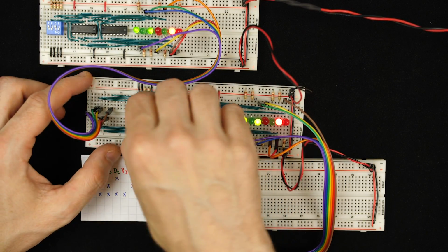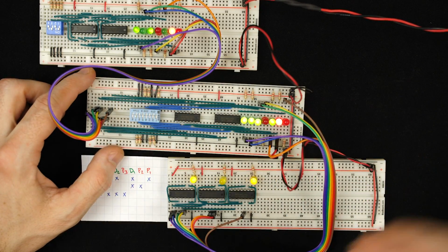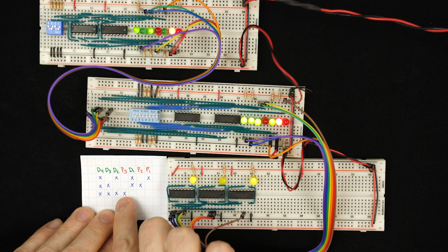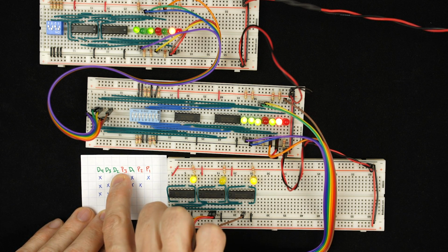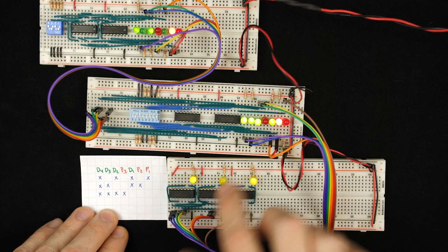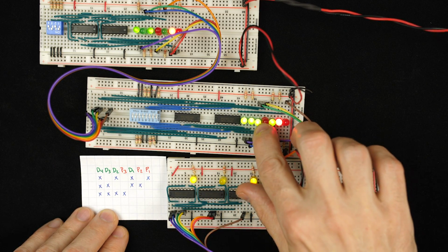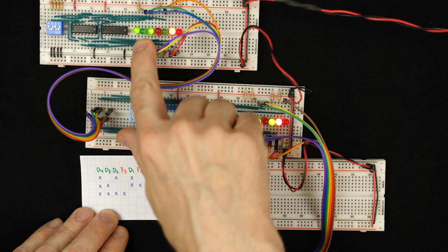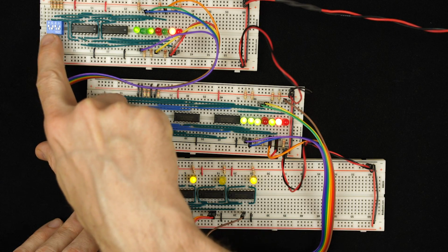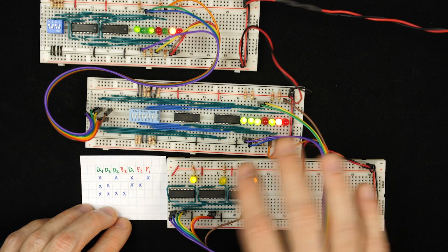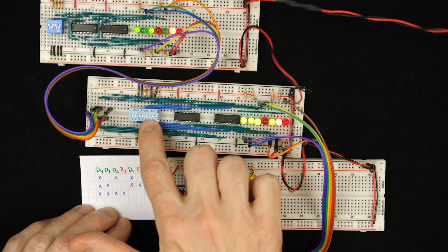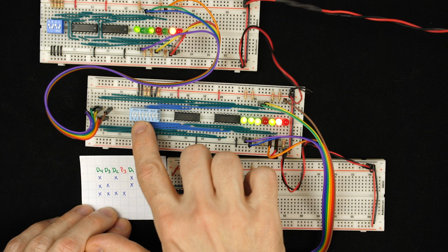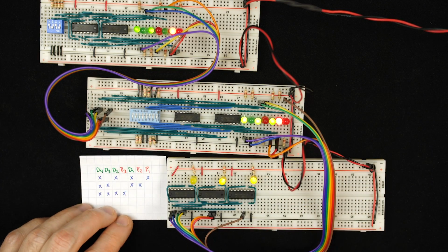Now, obviously, the one caveat is if there are 2-bit errors, then all bets are off. In this case, we're seeing parity bit 1 and 3 are wrong. The case where parity bit 1 and 3 are wrong means that D2 must be wrong. So if we try to do error correction here, if we flip D2, we'd get 1, 1, and then that would be a 0, 1. Well, the data was 1, 0, 1, 0. So we're not going to get the right answer in that case, but that's because we've got 2 errors. I've injected an error on D1 and D3. So we're not able to correct 2 errors, but if there's any single bit error, no problem.